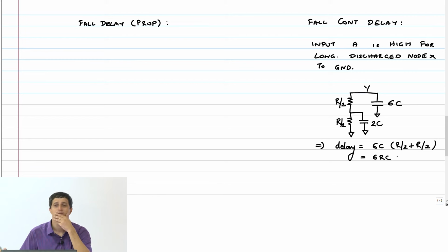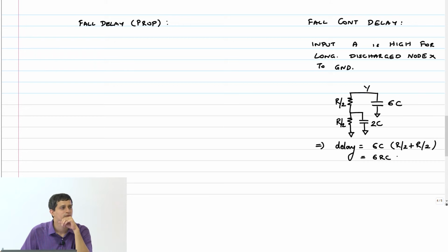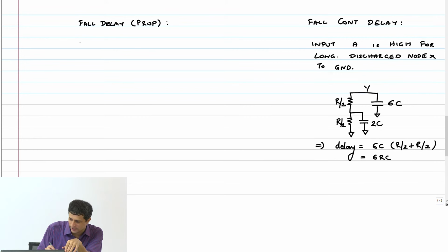That is 6 RC, right? You apply the same thing that I gave in the quiz, the initial condition where instead of 3 by 4 VDD, you make that ground. That capacitance term will just vanish, but the on-path resistances will still come for the other guys, correct? And therefore that becomes 6 RC, okay?